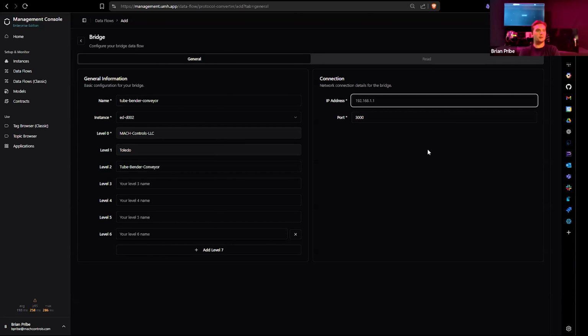When we were considering like the first connectivity phase of things, you definitely want to take an ISA 95 approach on the physical locations. That gives you the best idea about where assets actually are relative to like the virtual space within it. Now, once you have that structured on like physical assets where they are inside of the business, then you could deploy in any of your virtual paths that go with it. But when you're aggregating data from your business, like at the physical level, you want to have that map as close to reality as possible.